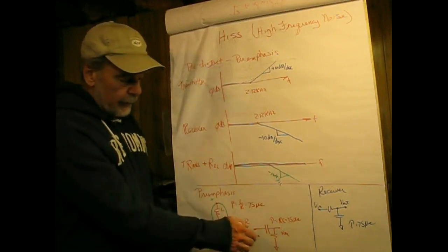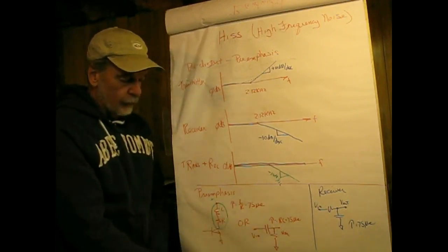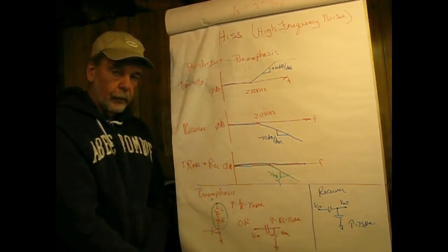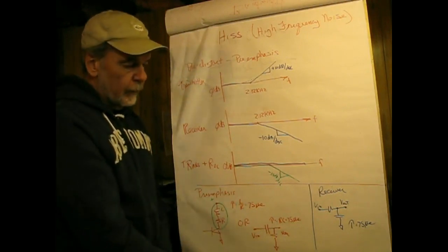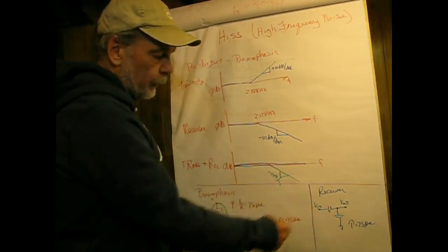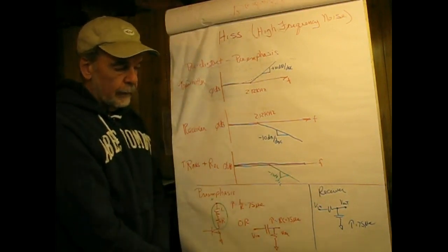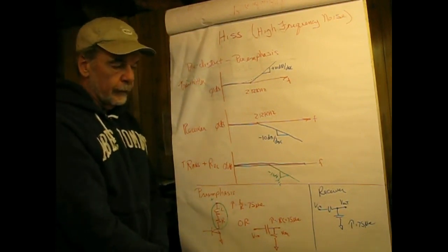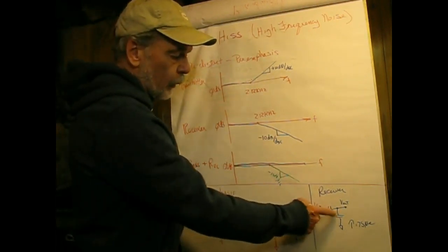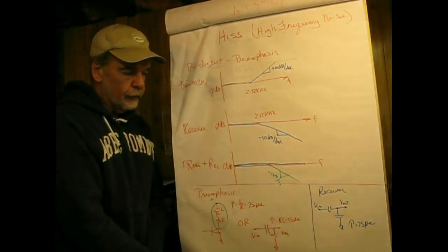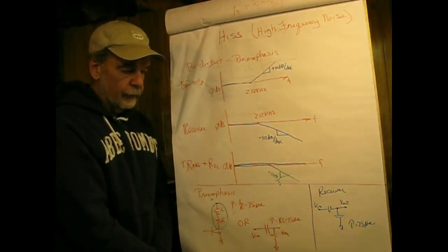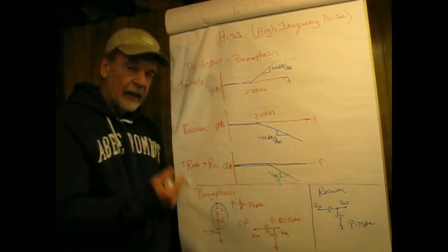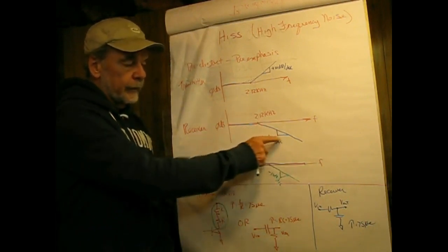Or you could look at it as a high-pass filter, a C in series with an R, and the time constant tau equals RC, also equal to 75 microseconds. Now in the receiver, this is the simplest de-emphasis network, an R and a C, and as you probably guessed, tau is equal to 75 microseconds. That basically means you have theoretically an infinite range of R and C values that you can use that will give you the time constant, and no matter what your values are, as long as the time constant is the same, you'll get this correcting factor.